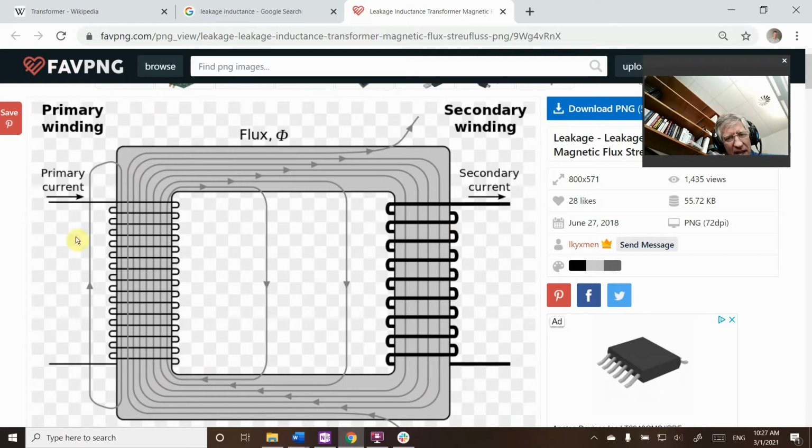So if I create flux right here, it is going to stay contained inside of this. Well, the permeability of a typical magnetic material is way lower than the electrical conductivity of a metal, and so we don't hold all of the magnetic field lines inside this material. You see I get these couplings over here, and I'm going to get these magnetic field lines that go outside.